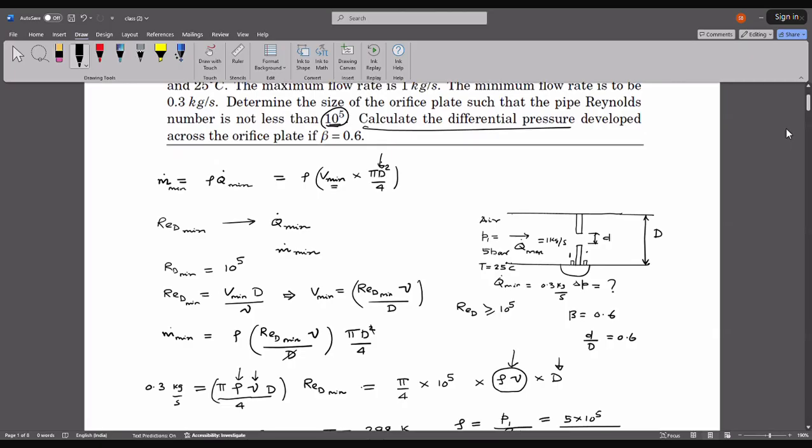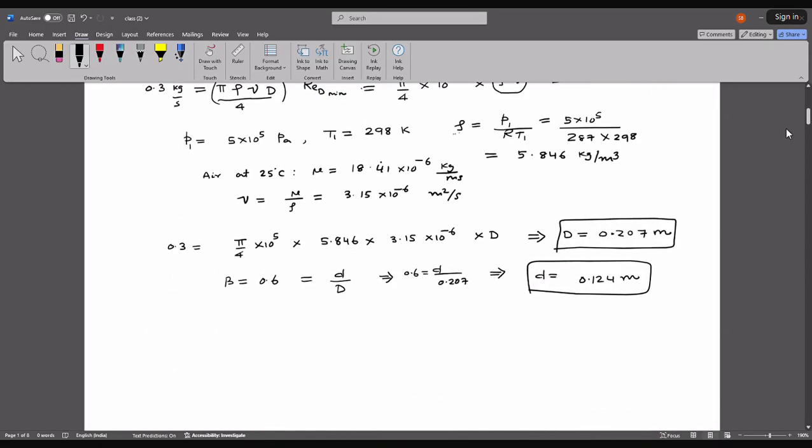So you have pressure tap 1, you have pressure tap 2 there, and you are asked to find delta P. For that purpose, we can use this formula that we had studied in the class, that the mass flow rate is flow coefficient times the area times the square root of 2 rho delta P. This is the formula that is there in the PPT.